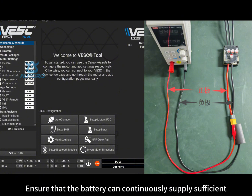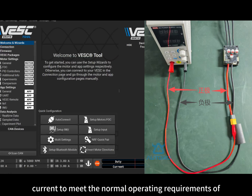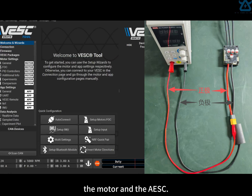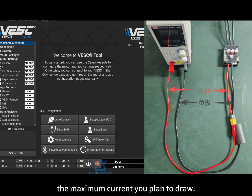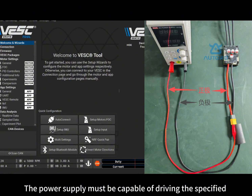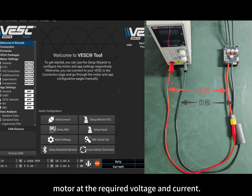Current check. Ensure that the battery can continuously supply sufficient current to meet the normal operating requirements of the motor and the AESC. The battery's current output in amperes must be greater than the maximum current you plan to draw. Motor compatibility. The power supply must be capable of driving the specified motor at the required voltage and current.